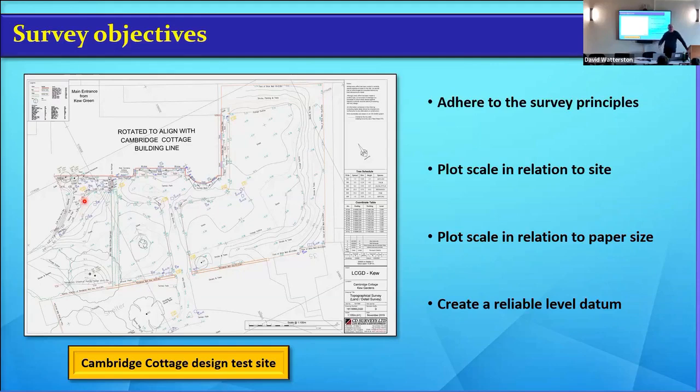So I think one of your challenges, if you still use this site, is, all right, you're going to redesign planting all around there, lovely, but what do you do about this area? How do you get around that? So I surveyed it all and then added it to the drawing. And the thing is, because you're restricted, if you make the ramp at the inclination it's designed for and the width, you will block the entrance into the building. And because it's, I don't know, is it listed or not, but anyway, it causes a real problem. So it's a real issue, and how do you get around it?